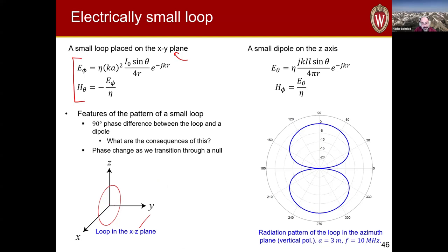If I look at the radiation pattern in the azimuth plane, I have that figure 8 shape radiation pattern, and I have vertical polarization along the azimuth plane as well. Now, in this case, by the way, the polarization along the positive Z direction, or towards the ionosphere, would be horizontal. So this antenna on its own would also be good for NVIS type applications, but you can also take advantage of its vertically polarized radiation along the azimuth plane to do some interesting things.